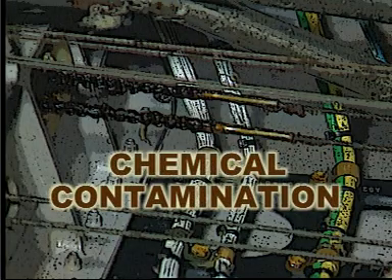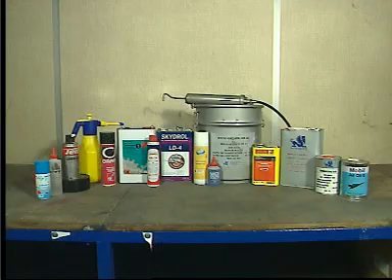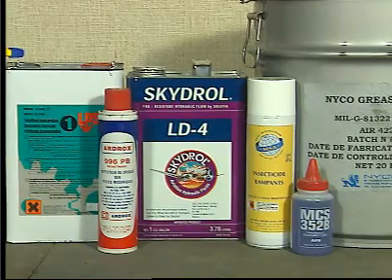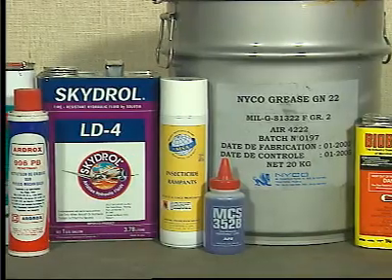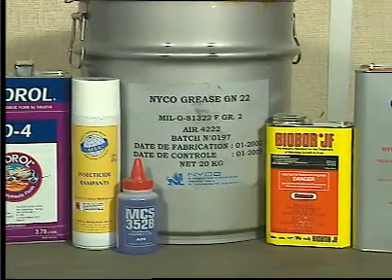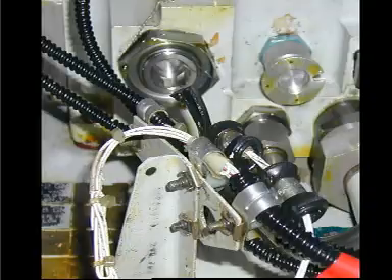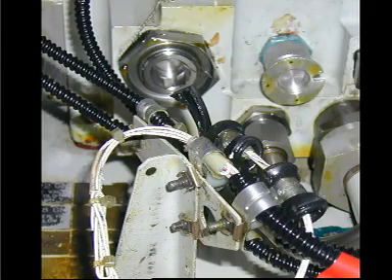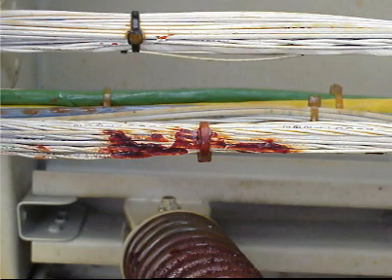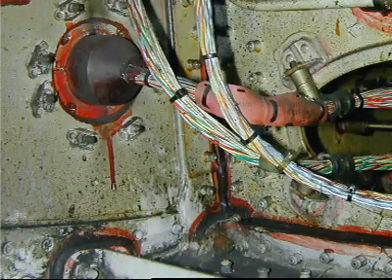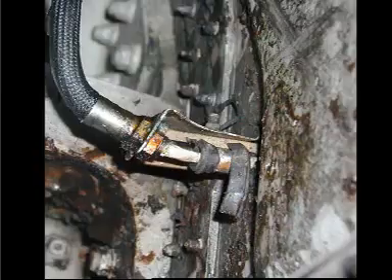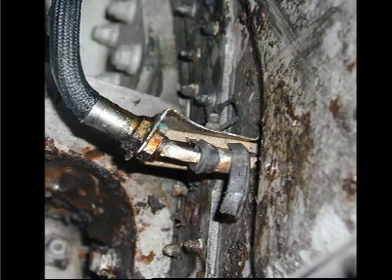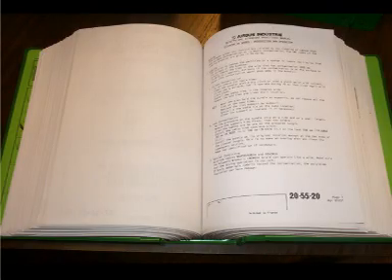Chemical contamination. Chemical contamination is a contamination caused by chemicals, liquid, grease and hydraulic fluid as well. Wiring in the vicinity of these chemicals ingress should be inspected for damage or degradation. For example, you must inspect the grommet of the clamps. The cleaning procedures of the Airbus technical documentation must be followed.